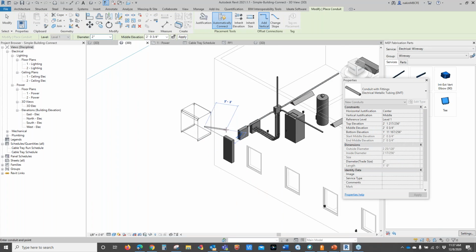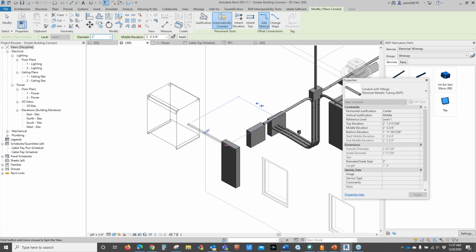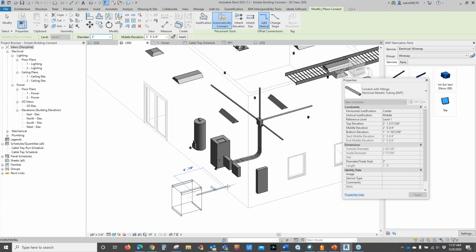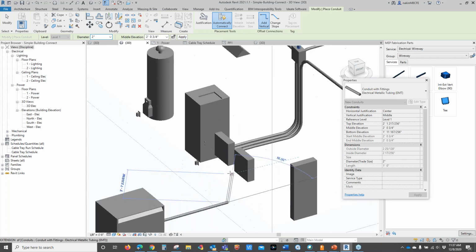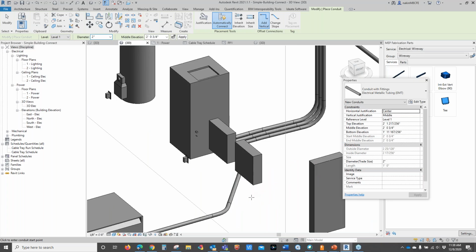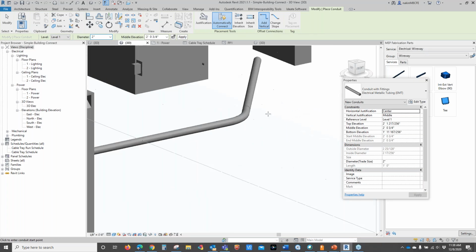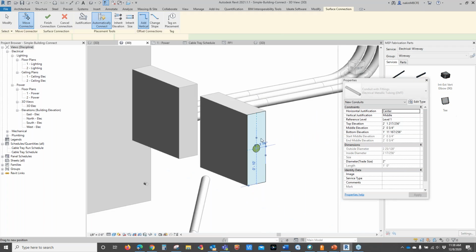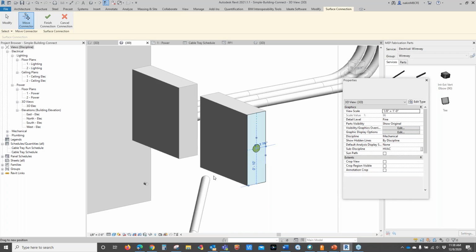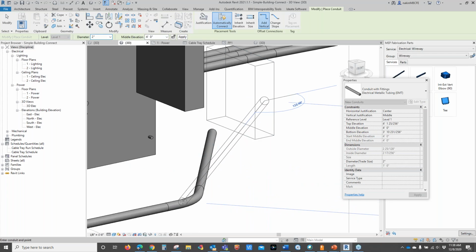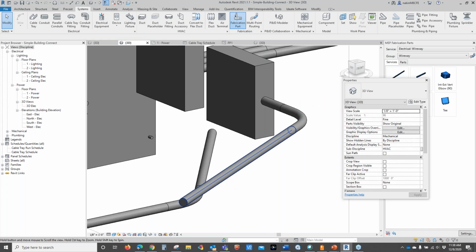Finish, pull that conduit from point A to point B. And I probably went below it, but I would come back in and select this panel, it's a conduit here, say yes, and then place it here.